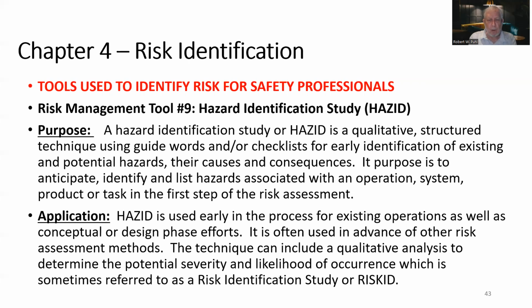HAZID is used early in the process for existing operations, as well as conceptual or design phase efforts. It is often used in advance of other risk assessment techniques or methods. The technique can include a qualitative analysis to determine the potential severity and likelihood of occurrence, which is sometimes referred to as a risk identification study or risk ID.